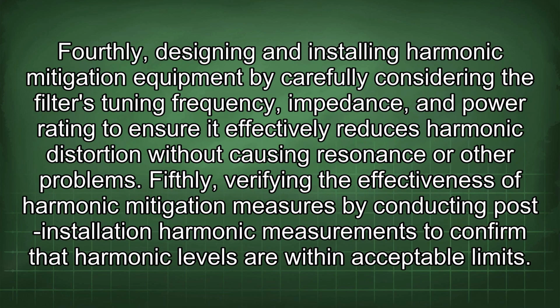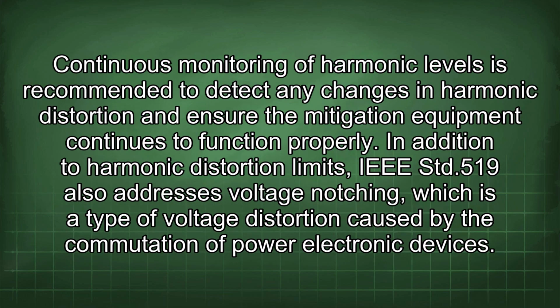Fourthly, designing and installing harmonic mitigation equipment by carefully considering the filter's tuning frequency, impedance, and power rating to ensure it effectively reduces harmonic distortion without causing resonance or other problems. Fifthly, verifying the effectiveness of harmonic mitigation measures by conducting post-installation harmonic measurements to confirm that harmonic levels are within acceptable limits. Continuous monitoring of harmonic levels is recommended to detect any changes in harmonic distortion and ensure the mitigation equipment continues to function properly.